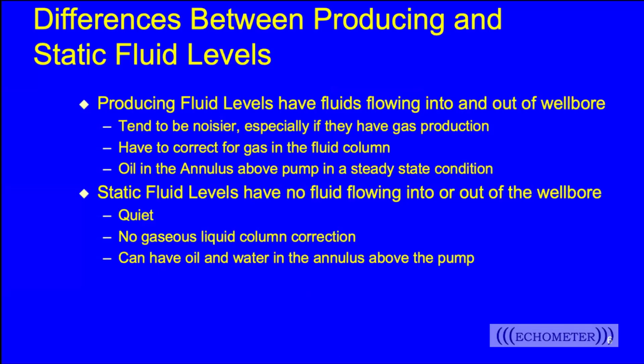Now, a static bottom hole pressure we get on a well that's been shut in long enough for the pressure in the wellbore to equalize with the reservoir pressure. That means there's no more fluid flowing in or out of the wellbore. The well's shut in, it's equalized to the reservoir pressure, it's static. So this also means that the well's quiet. It's easier to obtain a liquid level. You might not need as big of a shot, a fairly small shot, to obtain a liquid level. The liquid column is solid liquid. There's no gas percolating through that liquid column. There's no gaseous liquid column.